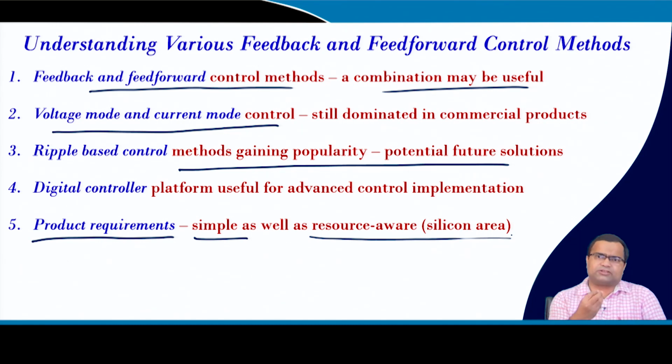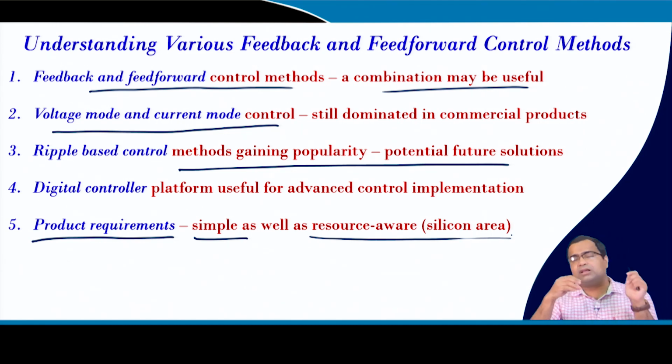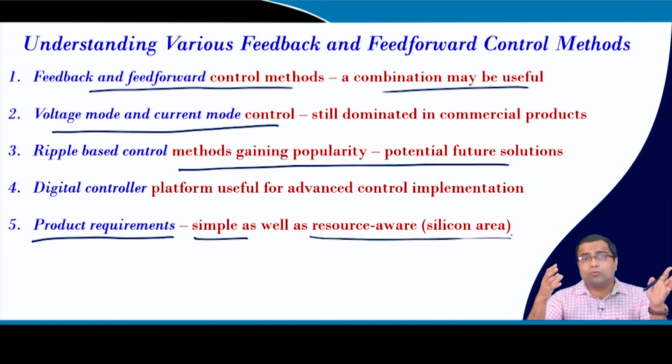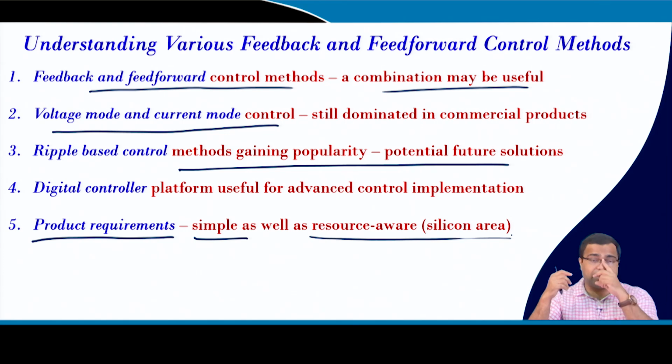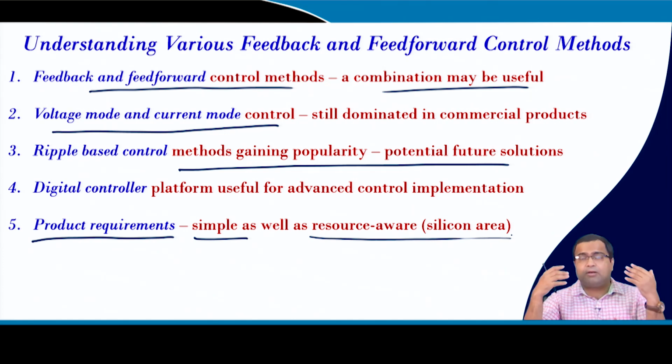Your controller as of now is an IC, but in future, along with the controller, you can consider the devices also as part of it. In a little higher power application, where we still use bulky off the shelf components, many of these can be combined into an IC to increase the power density, and that is the future trend. Sometimes people are now talking about integrated magnetics in the PCB itself.